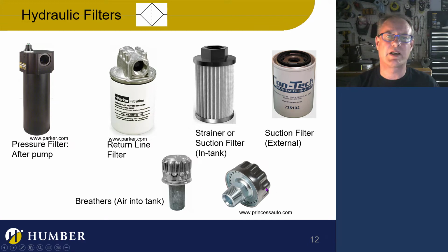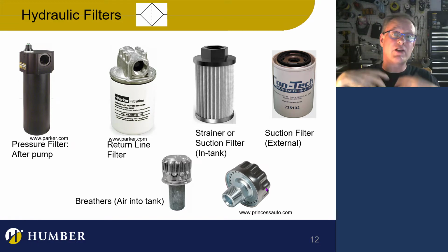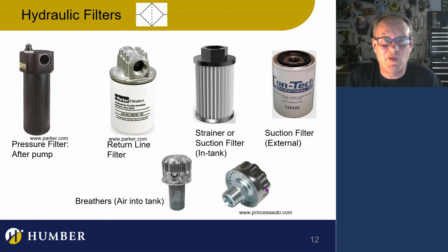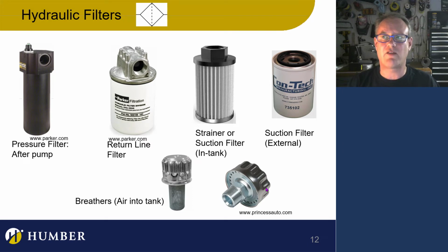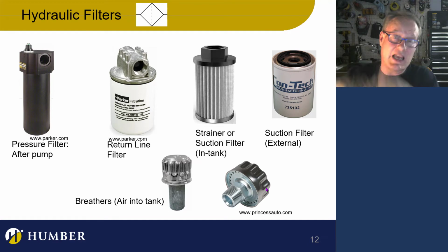And then we've got breathers. Breathers are really important because a couple of things that breathers do is they allow air pressure not to be built up in the tank, because air is on the top of the tank, and that air is going to get warm. It's going to want to expand. It's going to want to get out of the tank. So you want to let it out of the tank. So a breather allows air to get out of the tank. Now, the other thing is that when the fluid cools down and contracts a little bit, air is going to have to get into the tank.